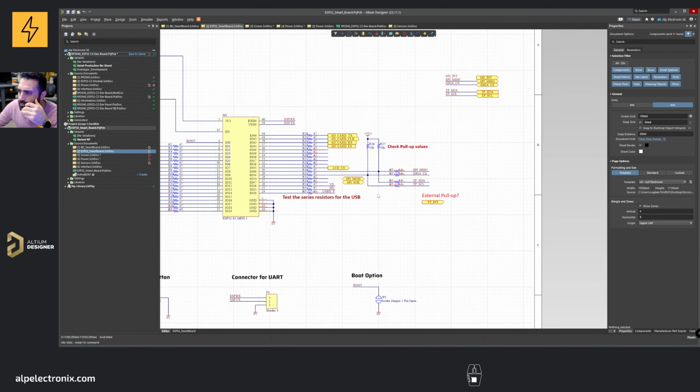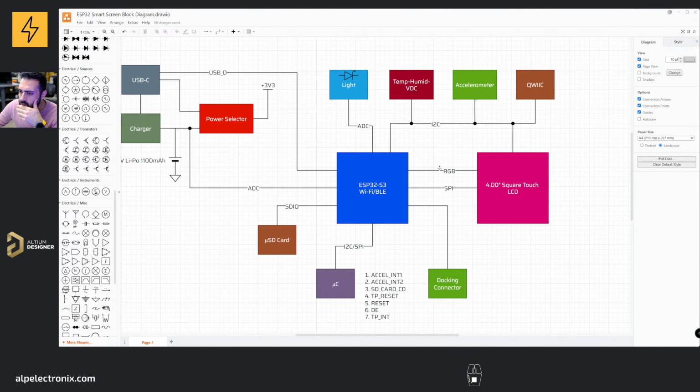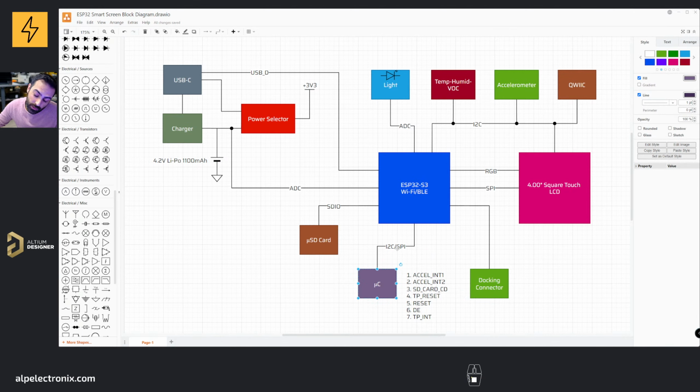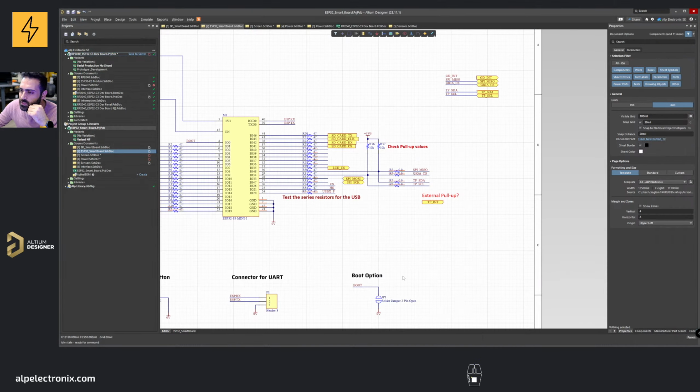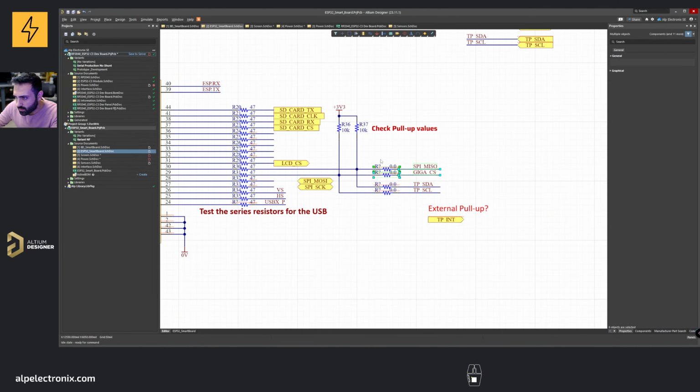This rest is okay. According to the block diagram, I said that the microcontroller will be connected through either I2C or SPI, but I think I2C is okay because I use the same I2C for these lines already, so it's good to use the same line to reduce the number of IOs actually used. So that's why I'm gonna remove this option.